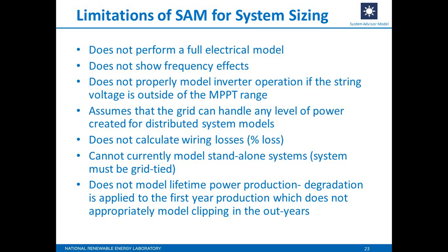First thing I should point out is that SAM is not a full electrical model of your system. So there are some sizing limitations inherent in that fact. It also does not show frequency effects, being not a full electrical model. And it does not properly model inverter operation if the string voltage is outside of the MPPT range of your inverter.